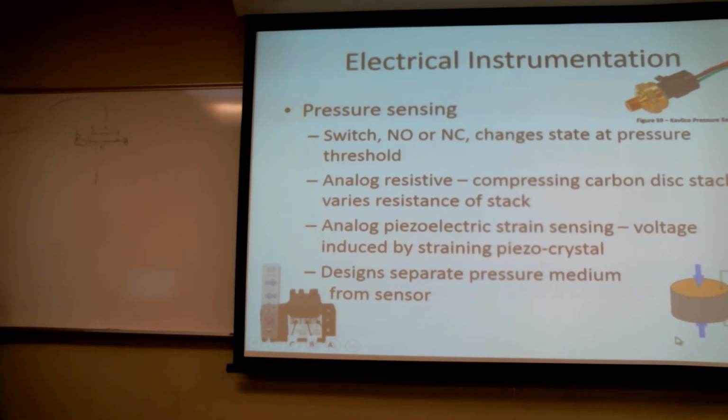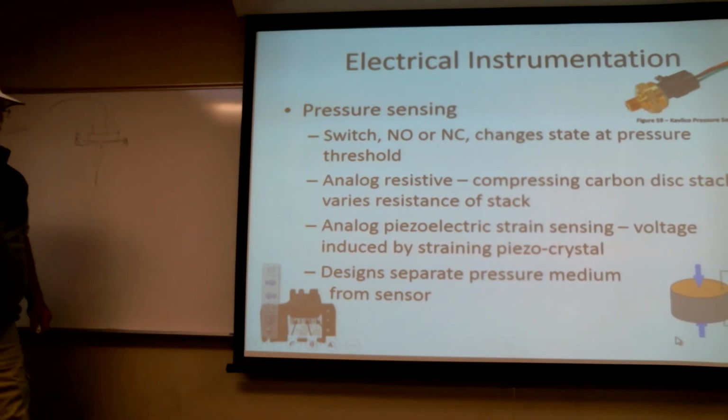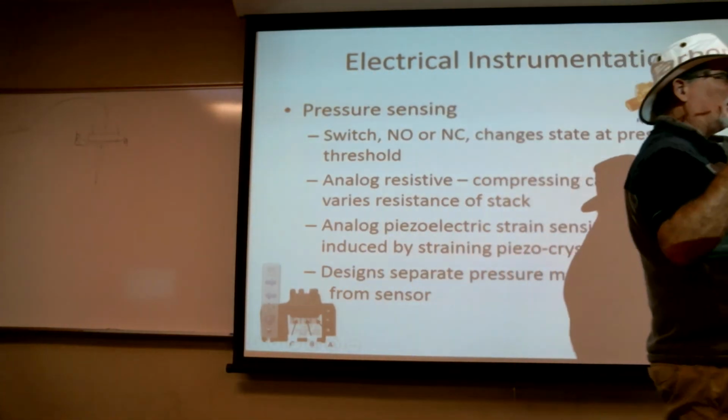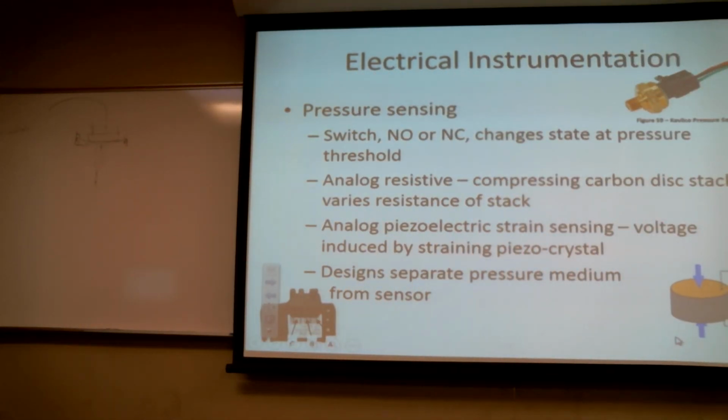These guys are so sensitive that I can actually make a 5-axis or 6-axis piezo crystal that I can use as a G meter that will measure down to 1/1000th of a G. In fact, I can buy the entire circuit completely set up, one little chip, that does it all and provides digital data out. You don't have to do anything other than glue the chip on, give it voltage, and read the data coming out, down to 1/1000th of a G.